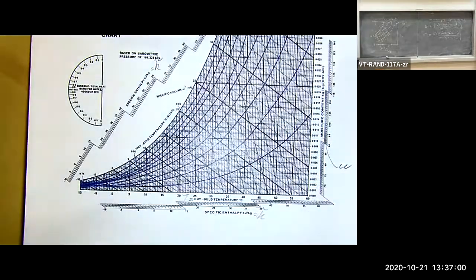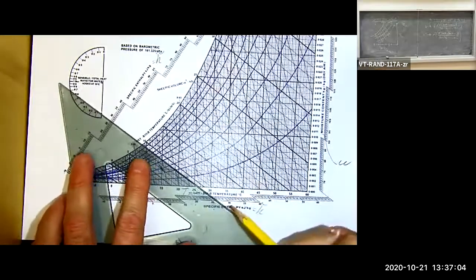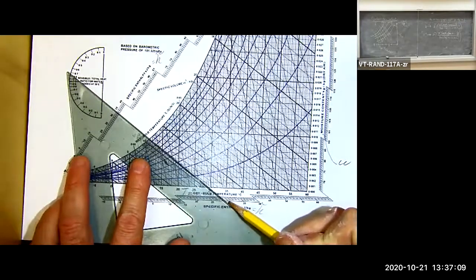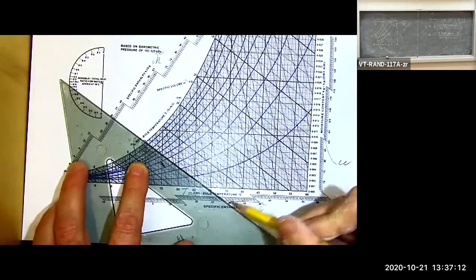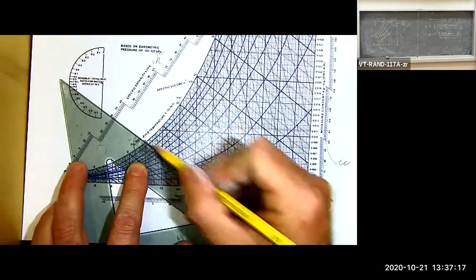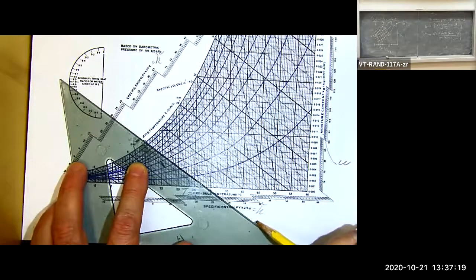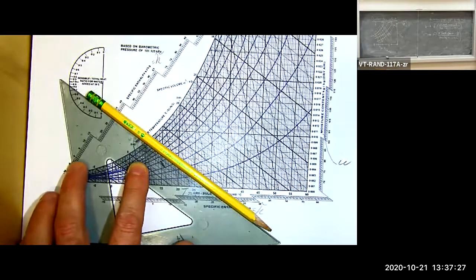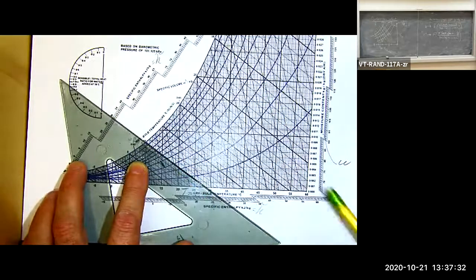And this is at an angle. How do you get the angle right? You line up, so let's say there's 30 kilojoules per kilogram of dry air. Let me match it up with the 30 right over here. This line right here represents the isenthalpic line, H tilde equal to 30 kilojoules per kilogram. So the lines of constant enthalpy, H tilde, go something like this. And you use the axes and the scales here to get the proper value, okay?